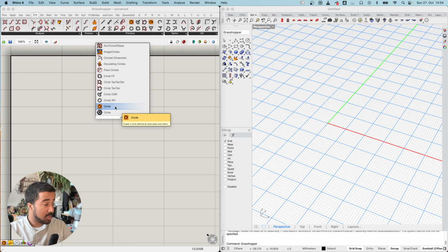So I will add a panel and select a different value for it. I can do this by double clicking on the canvas again and simply entering panel, and there I can double click, enter a number. Then I don't want to hit enter because that will just create a new line. Instead, I want to simply left click out of this panel, and then I have my panel set with my input, and I can start connecting this panel with our radius input of the circle.